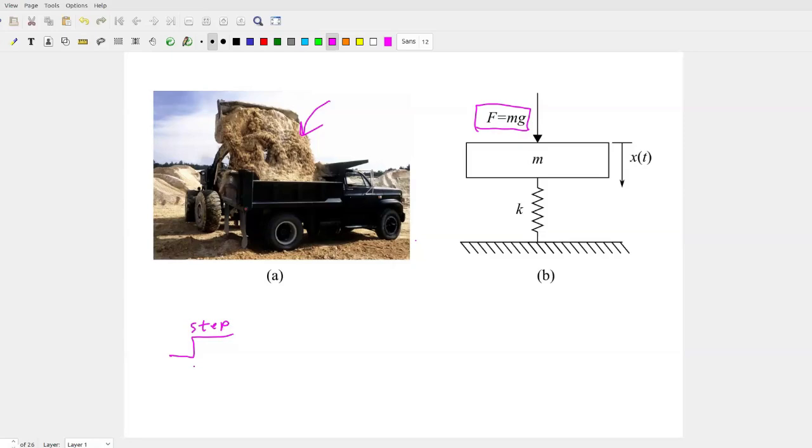So our undamped displacement of that system is going to be x of t is equal to 1 over k, 1 minus cosine of omega n t. I'm going to close out in slightly bigger brackets.